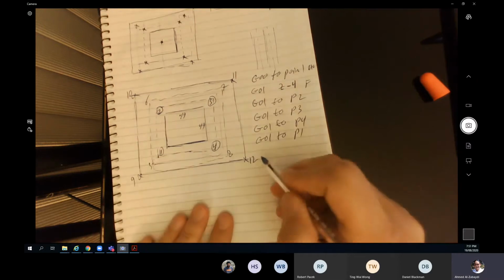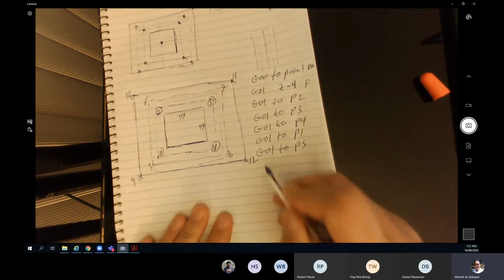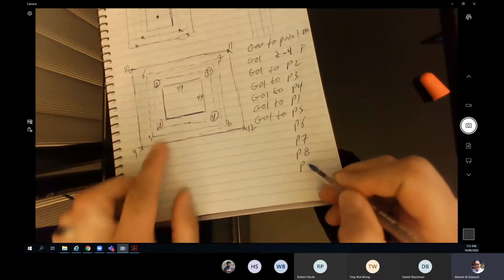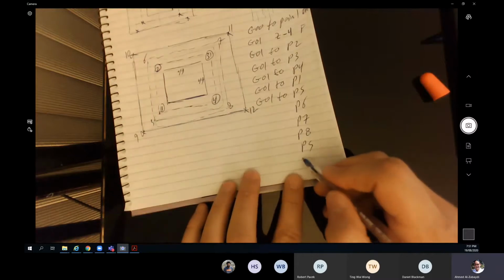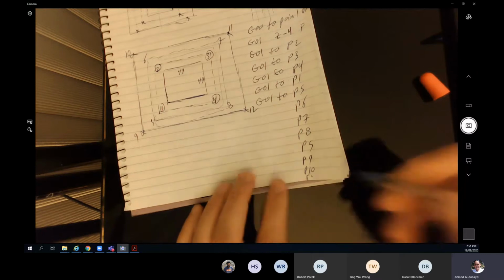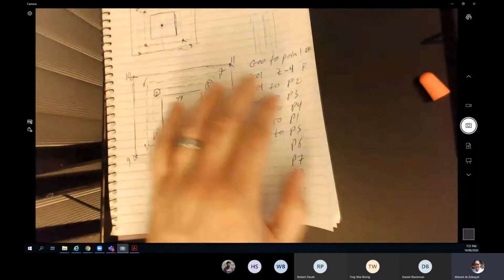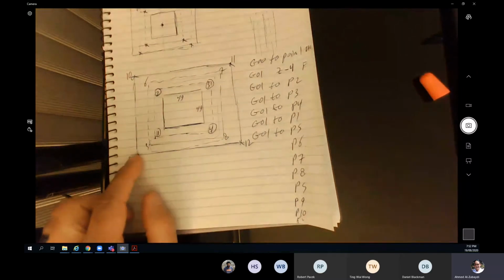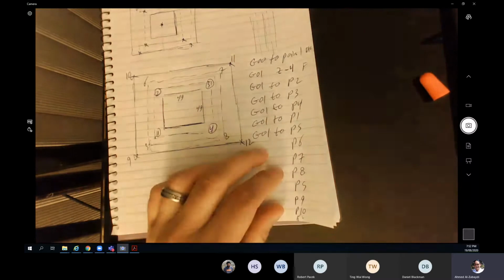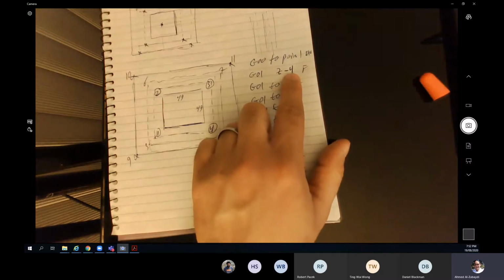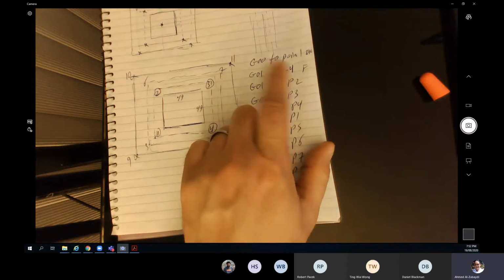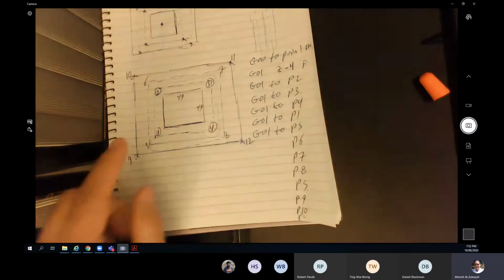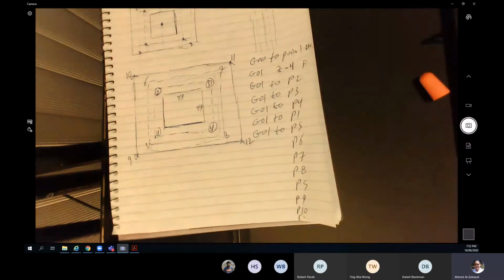Otherwise, we're not going to have removing of this material. G01 to point 5, 6, 7, 8, 5. Then from 5 to 9, 10, 11, 12, and then 9, done. Now, this was to the depth of minus 4. Then we can go back the opposite way, or you can take the cutting tool to this location once again, copy paste the same code, just change the Z value to be negative 6. Just copy the same code and put it down. When you finish, you take the cutting tool to the height of 10 millimeter, push it away, and turn off the machine.